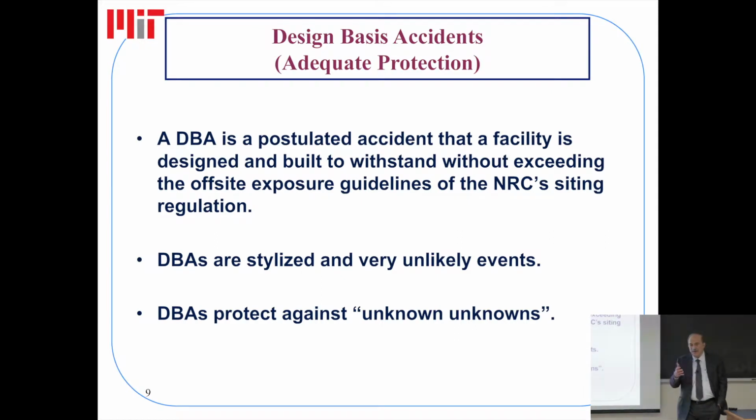As an example, we've had now several thousand reactor years of experience with piping. We have never seen a large pipe break anywhere in the world. And in fact, there was some serious research done at Lawrence Livermore National Laboratory years ago, where the saying "leak before break" was established. In other words, such a large pipe will never break. It leaks first, which means, of course, that the plant personnel know that it's leaking and they will take appropriate action.